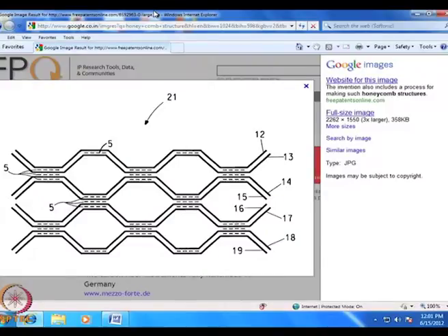Secondly, the most important part is die design. I had shown you that diagram where they are extruding ceramic pipes. Now, you see, by injection molding, by extrusion, we can have honeycomb structures.